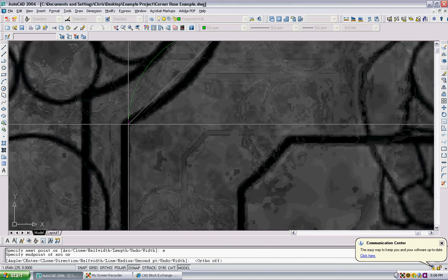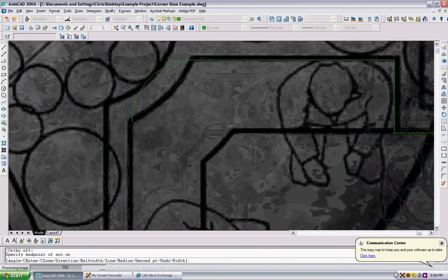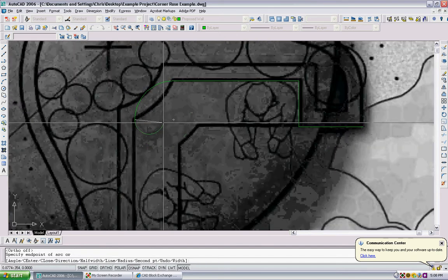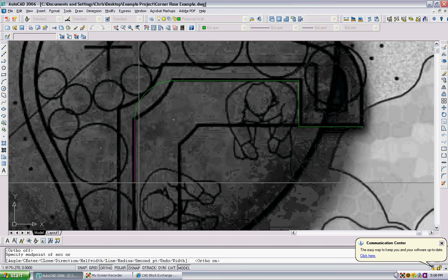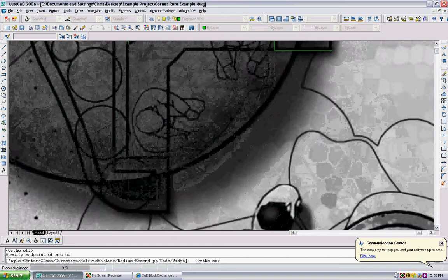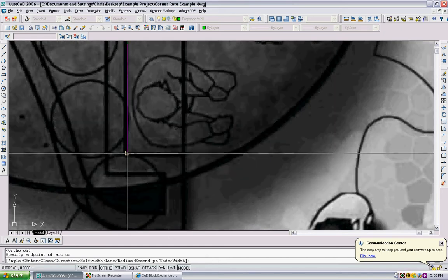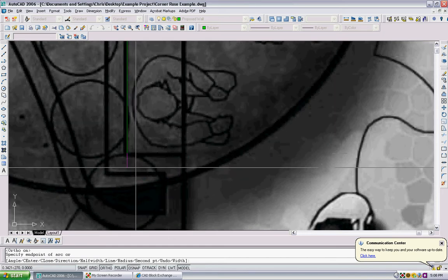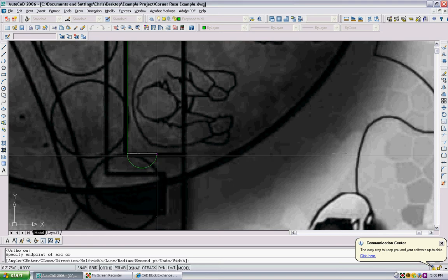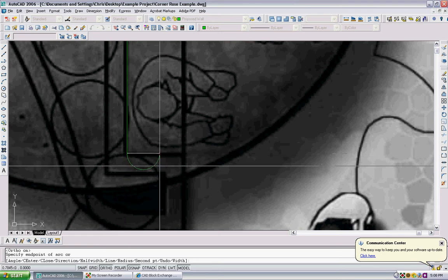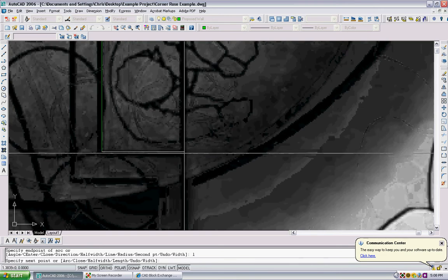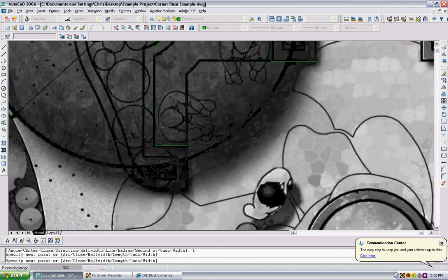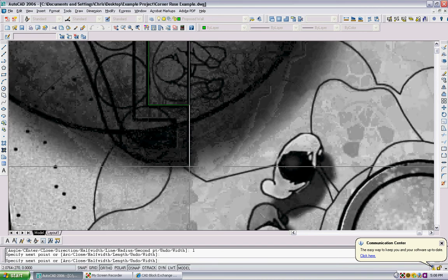And we'll fix that curve, that radius there. We'll pull it to the appropriate side. Turn your ortho back on and come back down. Oop, nah, yeah, it's still doing the arc because I didn't tell it to go back to line. Tell it to go back to line. You hit L, enter, and put your line back on. Take away the arc. Come down.